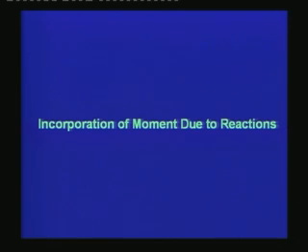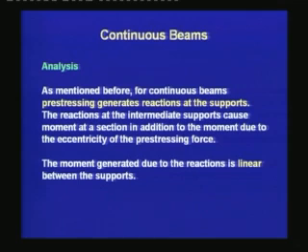The next important aspect is the incorporation of moment due to the reactions. As mentioned before, for continuous beams, prestressing generates reactions at the supports. The reactions at the intermediate supports cause moment at a section, in addition to the moment due to the eccentricity of the prestressing force.